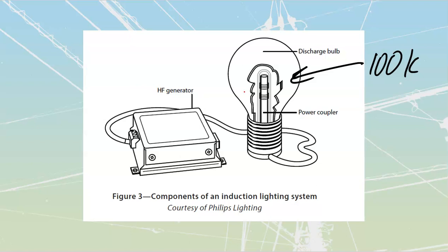There is also another disadvantage that has not been mentioned, and that is the electronic noise and the harmonics. We as a society have so many electronics that contain what we refer to as switching power supplies. These are semiconductor-driven circuits that are utilized in things like any type of computer, any power supply for microelectronics, all those little wall warts that you plug your electronics into, the USB sockets that are built inside of receptacles. All of that stuff starts to cause junk on our electrical system. We call it harmonics, or we call it electrical noise.